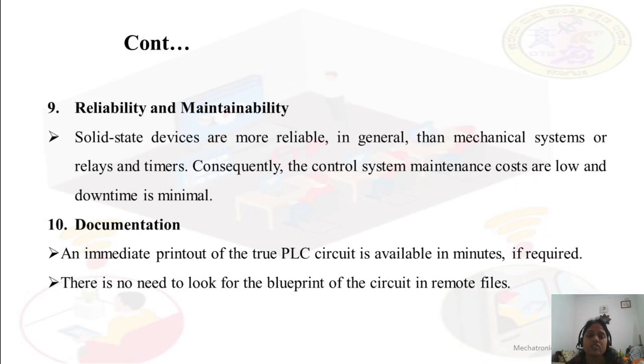The next advantage of PLC is reliability and maintainability. Solid state devices are more reliable in general than mechanical systems or relays and timers. Consequently, the control system maintenance costs are low and downtime is very minimal. See, in the mechanical system, that is in the relay logics, the wear and tear of the components is more compared to PLCs. The solid state components are more reliable than mechanical system components.